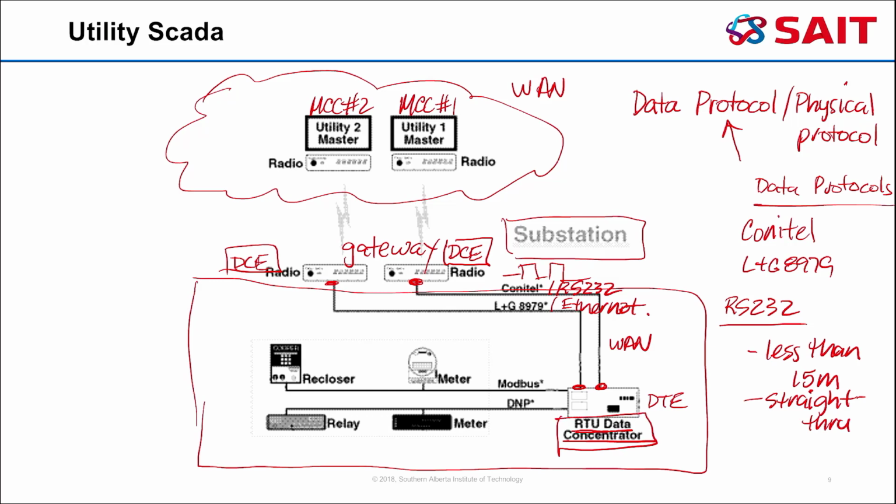And that is to say that when it comes to RTUs nowadays, because they're in environments where the sensors that are picking up all of their variables for analog data like voltage, current, temperatures, pressures, and all that, are smart sensors, you'll find that there's not a whole lot of discrete input loops, or DI connections.